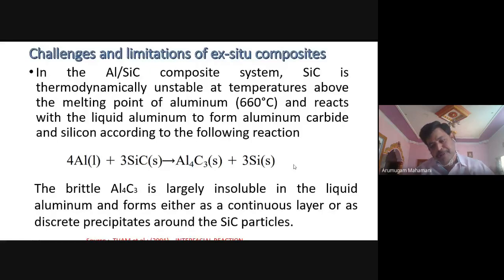Because of this, many people will be confused. They will do it in their laboratory, but what happened is these people did not control this temperature. Simply keep on melting, applying heat, everything. Okay, this is the problem, because this intermediate component formation reduced your mechanical property.